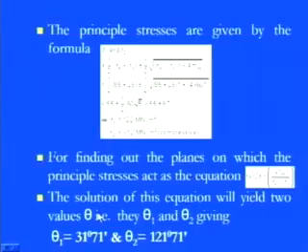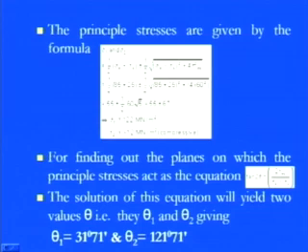that is 31.71 degrees. Like this cylindrical object which I showed you previously, if you tilt it by 31 degrees, then whatever planes are coming, these are the principal planes, and the stresses there are sigma 1, which is tensile in nature with a magnitude of 122 meganewton per meter square, and the compressive principal stress 2, directed towards the element, which has a value of 12 meganewton per meter square. You can also calculate the theta 2 value just by adding 90 degrees, because both are perpendicular to each other, as these are mutually perpendicular stresses.